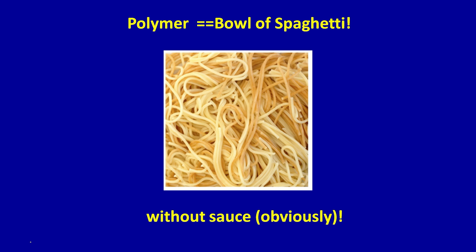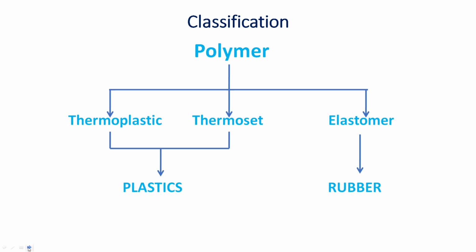That is why they are called thermoplastics. If you heat them up, they become very plastic. And then you have thermosets. Thermosets are the opposite. If you heat them up, they cannot be reused. They set once, like bakelite, which is a thermoset used in power switches. There are many thermoplastics: polyethylene, polyvinyl chloride, they are all thermoplastics.